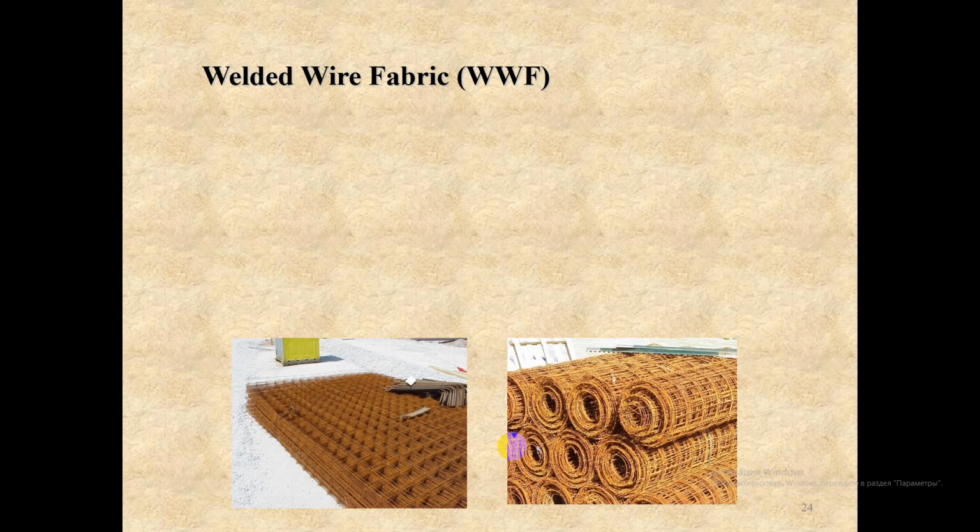Structural members that require only small areas of reinforcement can be reinforced with steel fabric, which can be supplied in sheets or rolls. Where exposed ends of fixed steelwork are present, such as this vertical starter bar, plastic mushroom cups are fitted as a temporary measure to prevent operatives from injuring or impaling themselves.